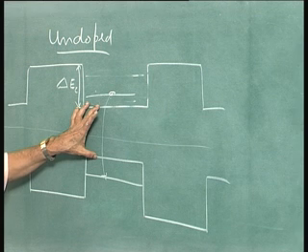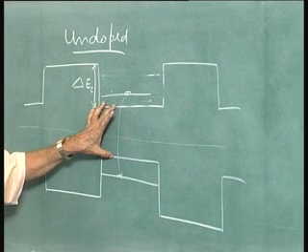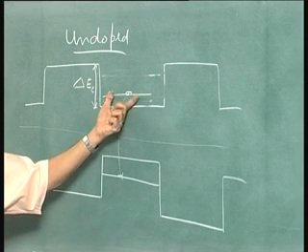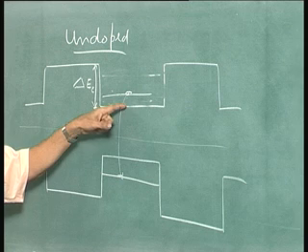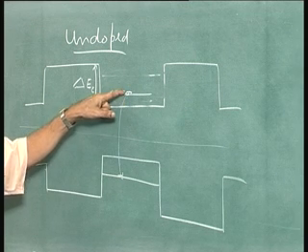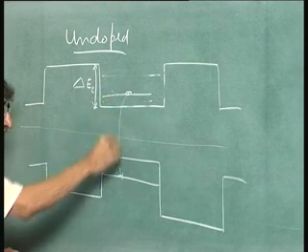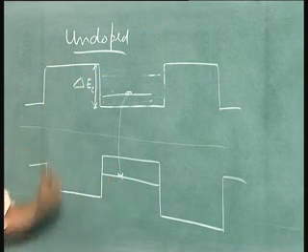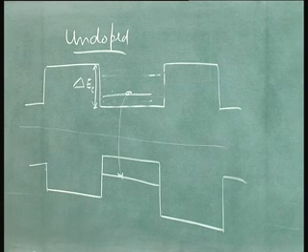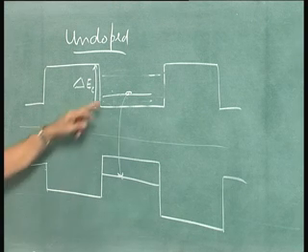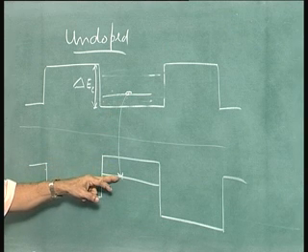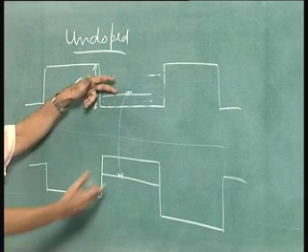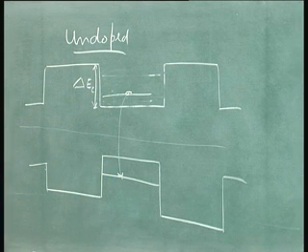When you confine them in a well like this, these electrons are above that band edge, that is the allowed level. Now, if you allow that to make a transition, that is when they recombine, they will get transferred from this level to that level, and the gap is more. So, if the gap is more, what have you achieved? The light emitted from here to here actually has a wavelength less than that corresponding to this wavelength, because energy is more, wavelength is smaller. That means you are pushing towards the visible range. So, you can get light of different wavelengths by making combinations of these things.